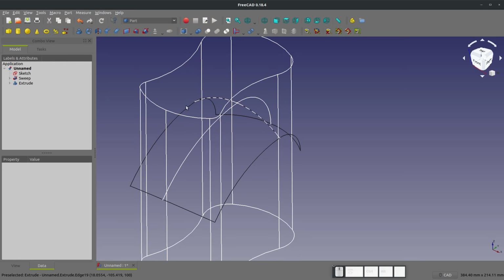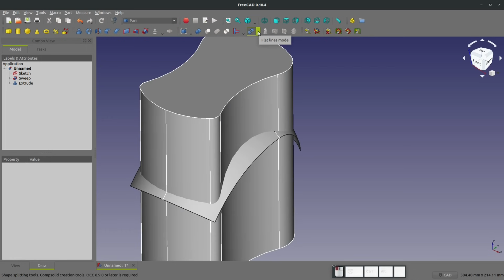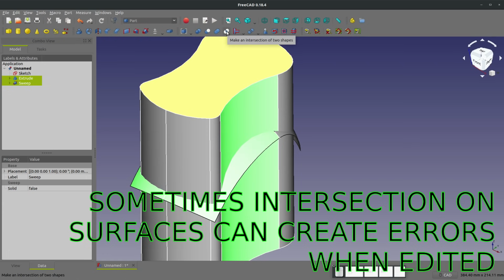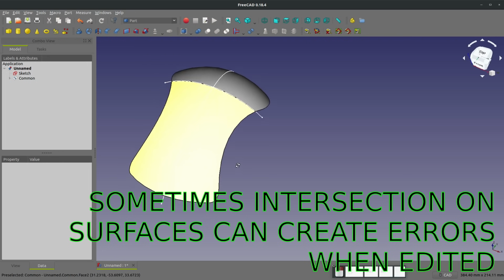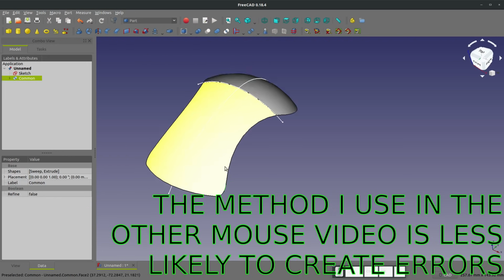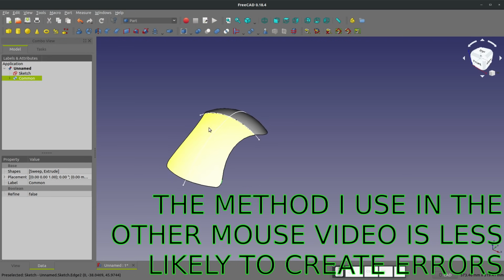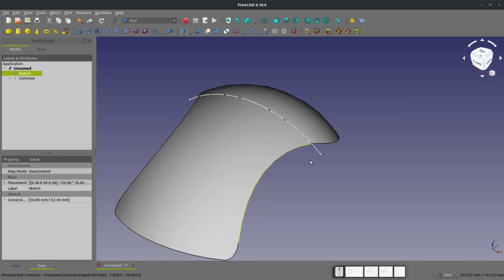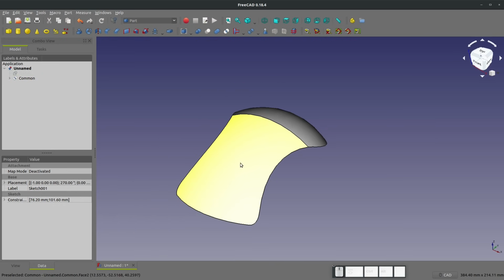Okay, the point is I just want my solid completely intersecting my surface. I'll change my view back to as is, right? So I have my surface and my solid, and if I choose both, let's create, there we go, an intersection. And I just kind of trim my surface to be exactly how I want it to be, right? You can also do an extruded cut or some other kind of Boolean. So don't think that this is the only way to do it.